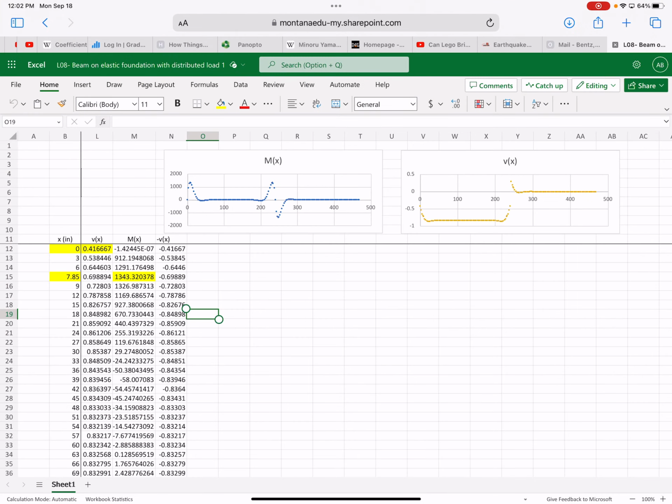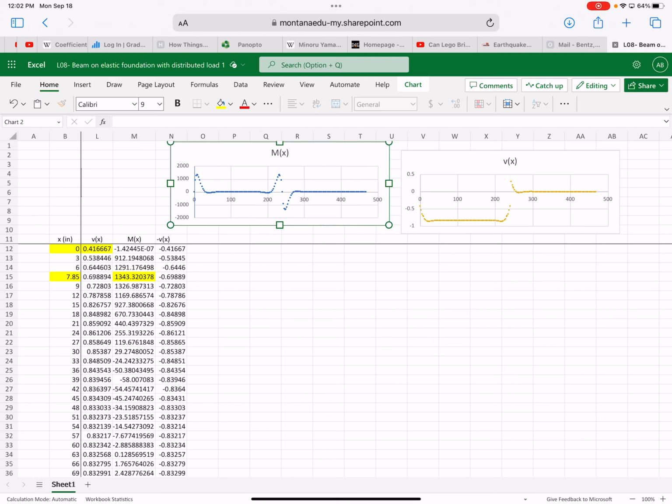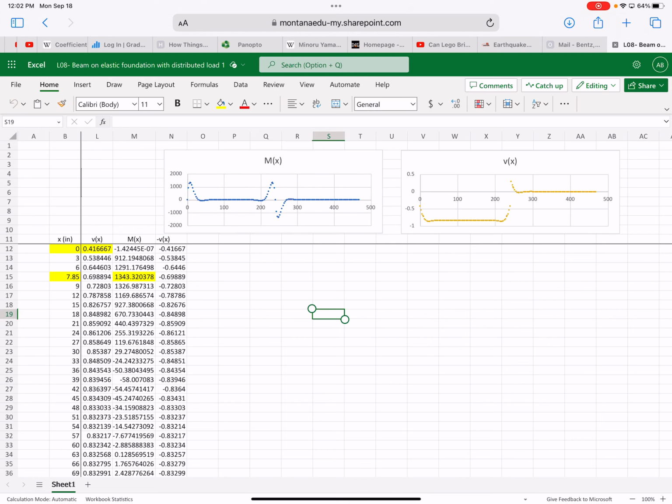So going back to that, right, we can see that trend. You can see that trend plotted in the moment diagram. And then in the deflection plot, it does show a trend similar to what I was trying to sketch the other day in response to the moment, where it just kind of flattens out within the middle. The only difference is it's obviously not zero. You have that magnitude that we calculated, and then towards the end of the beam where we calculated the deflection, it was like half of the value in the center, right? So we can see that trend when we plot it too. So this is what it looks like, where you just have a little bit of curvature at the very ends of the beam associated with where those moments are, and then it kind of flattens out.